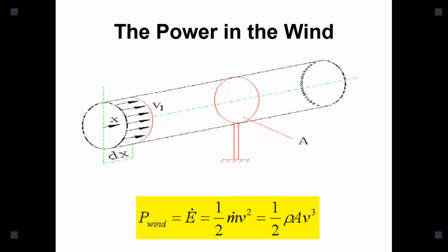Here, that is the mass. The mass is actually density times the volumetric flow rate. Density is dependent on temperature; it is generally a function of temperature. That is the reason in some cold countries, more wind energy can be generated in the winter season, because the air is very thick. The kinetic energy content in cold air is much higher compared to hot air.